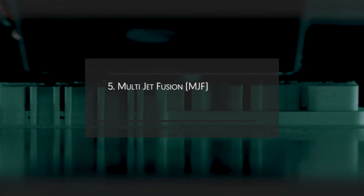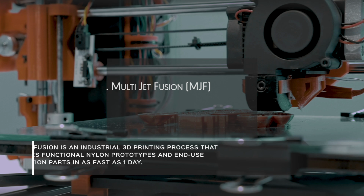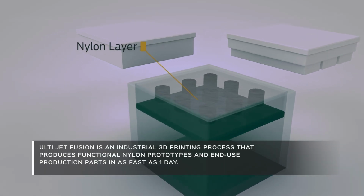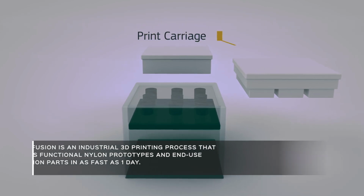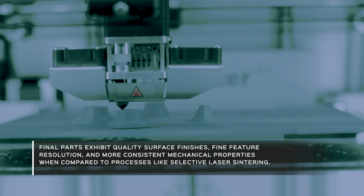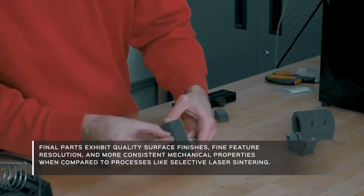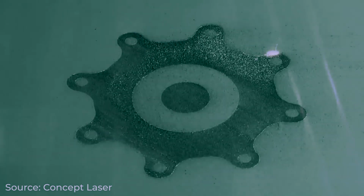Multi-jet fusion, MJF. Multi-jet fusion is an industrial 3D printing process that produces functional nylon prototypes and end-use production parts in as fast as one day. Final parts exhibit quality surface finishes, fine feature resolution, and more consistent mechanical properties when compared to processes like selective laser sintering. MJF printers offer fast build times.